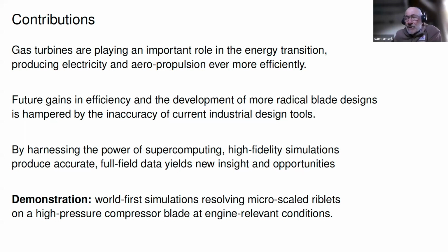This was a very serious thing, because if the compressor stalled, the fire went out, and the airplane had to dive to a very low altitude before it could do anything again, even if the engine would start. So I'm just wondering if your riblets would control or exacerbate stalling effects.